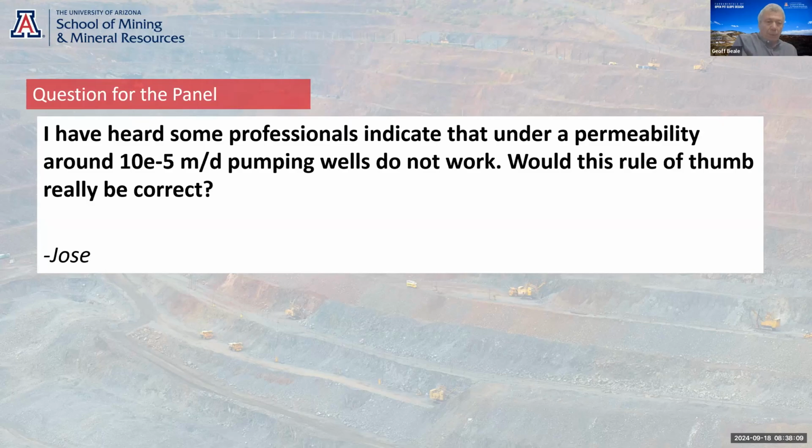There's several projects I work on where we have lines of pumping wells to depressurize silts and clays, and there's a couple of them where we have also vacuum wells to depressurize silts and clays, and we get very little yield out of them. But if we have the wells close enough spaced, we can do it. So again, if you've got a large scale dewatering system, that permeability, it's not worth putting wells into that. But if you have a need to depressurize a clay and you elect to use closely spaced pumping wells, then maybe you can do it.